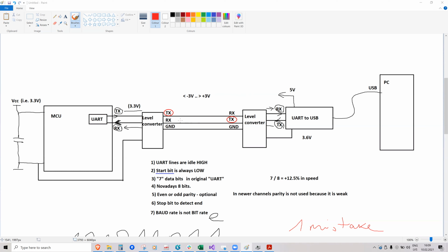It's true, you can use a voltage divider, because these are complementary metal oxide semiconductor inputs, which don't consume almost any electricity. So yes, in one direction you can use a voltage divider, but in the opposite direction, from the smaller voltage to send a signal to a higher voltage, it can cause problems.